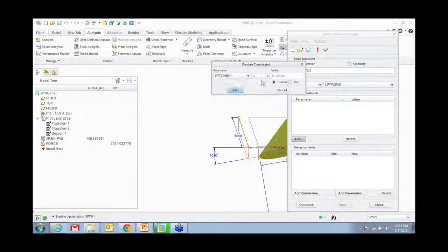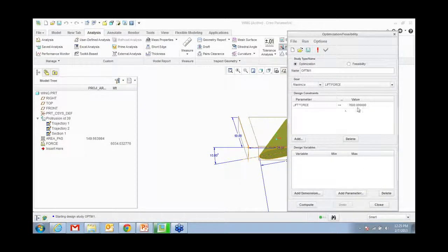You see at around 15 or 17, the value is maxing out. So that's a good value. So you place your cursor, it says when it is 16.11, the lift force is the highest. So you go ahead and then optimize it. So you say optimize, I want to maximize the lift force.